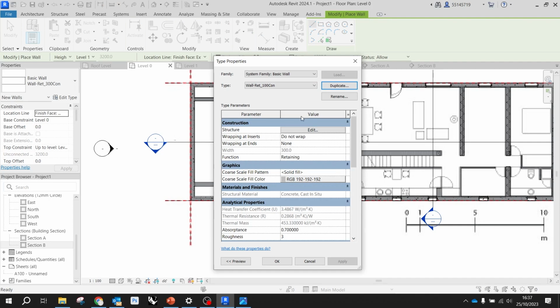The cool thing in Revit is you can also dig into the structure, change the size and the thickness of different layers, for instance, the insulation versus the finishings and so on. They all carry properties. So this is great for checking the cost of materials, changing the type of materials, for instance, the type of insulation you want to use, but also for environmental analysis, right? Because there are environmental tools inside Revit that will pick up on the families that you use that carry different properties.